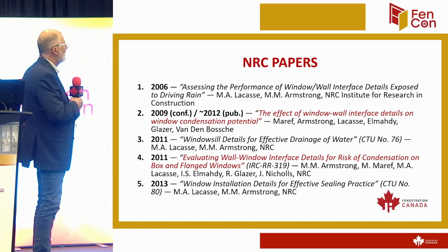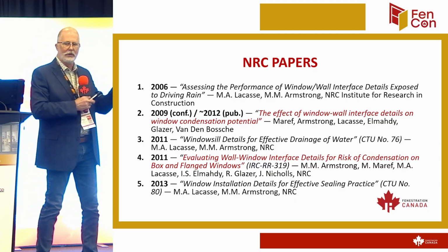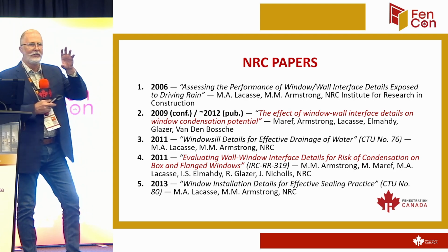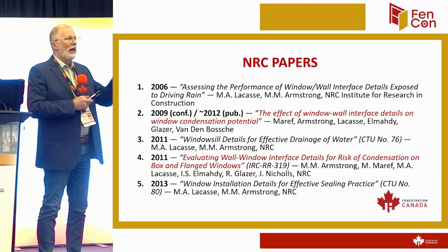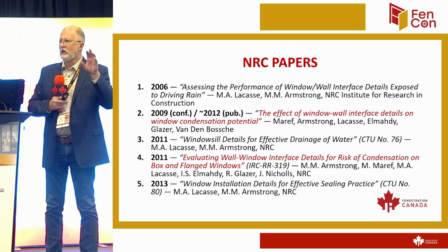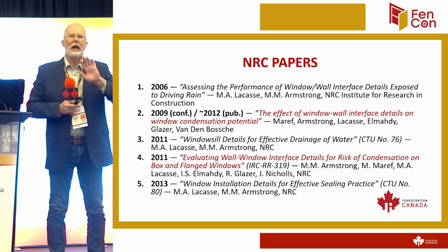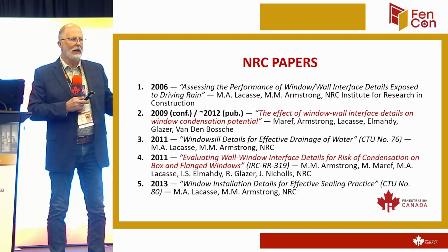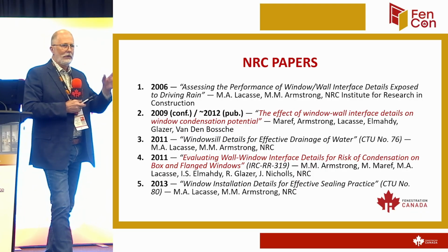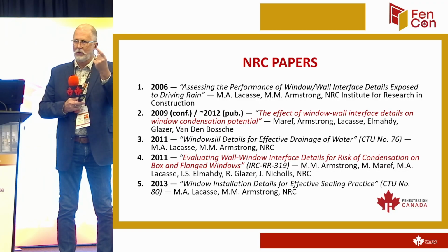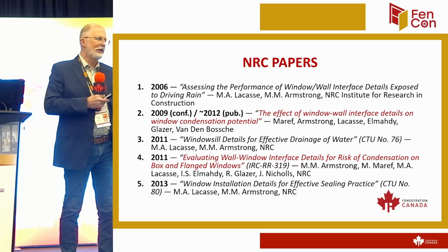So they did all these studies. So for their design with window interface details, window condensation potential, they look at the window design and they said, if we don't insulate the sill, what happens to the temperature on a minus 30-degree day? So what would you guess, and we're not talking any wind, so this is not wind related, this is just what would happen with convection only, right? So you've got a dead air cavity with no insulation. You have another one that they filled with fiberglass, and you have a third one that they filled with spray foam.